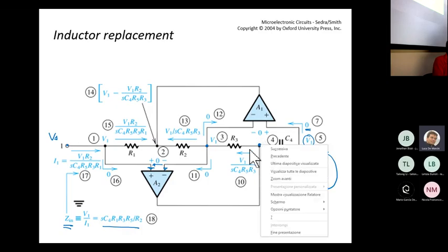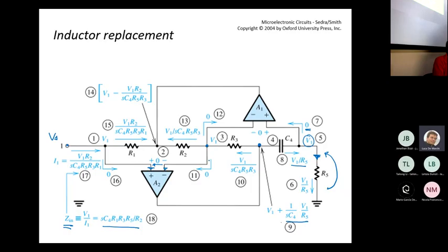So you have the voltage here, you have also the voltage here, because again it is V1, so you can compute the current which is flowing through the resistor R3. The current is given by this expression, and this current is the same current which flows in R2, because no current can flow in this path, no current can flow in this path, so there is no alternative path for this current but the one consisting in R2.